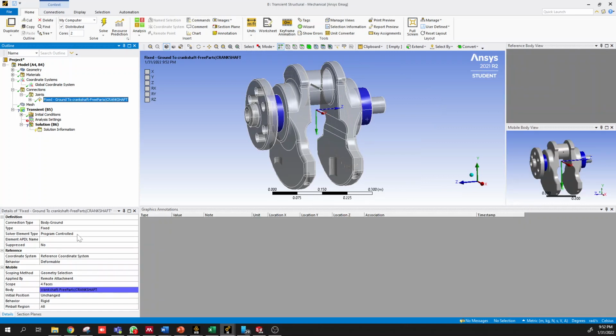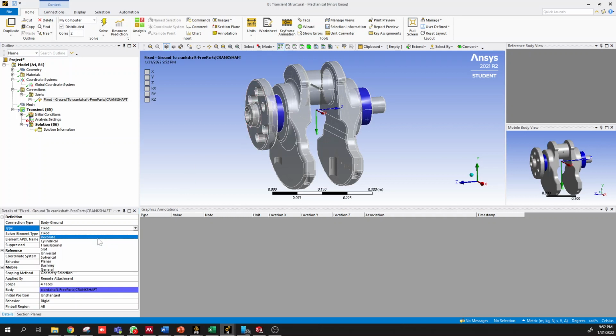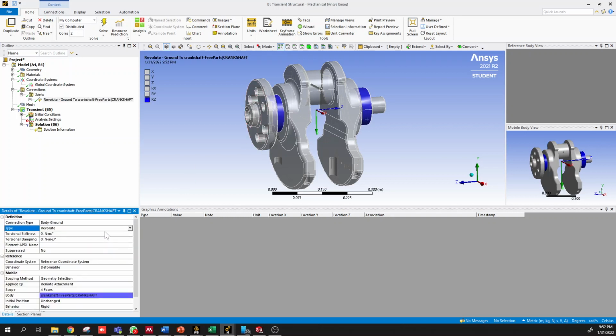This is why. We forgot to tell it what kind of joint this is. So we've assigned surfaces here, and we need to say that it's a revolute joint. By default, it will say fixed, and we want a revolute joint, meaning it's a cylindrical constraint. That's the only setting that I forgot to mention before we moved on from this menu. So we can say revolute cylindrical. The difference between these two is that one has an axial constraint and the other doesn't.